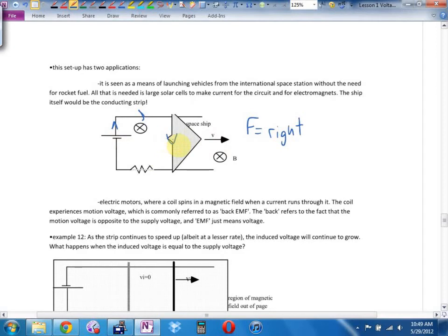And now we're starting to look at how some of the new roller coasters have magnetic braking. They brake you using this force, which is great because there's no moving parts. It's very smooth, and as you slow down, the force decreases, so it brings you to a very smooth stop. The initial jerk's really hard, and then it's easier.